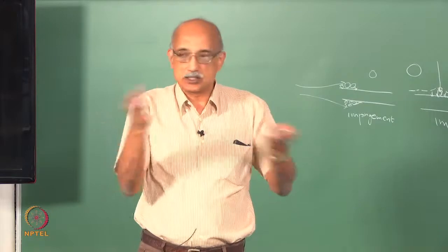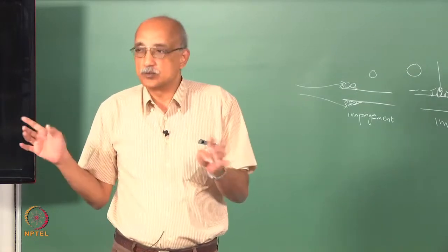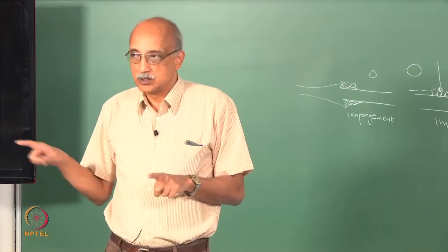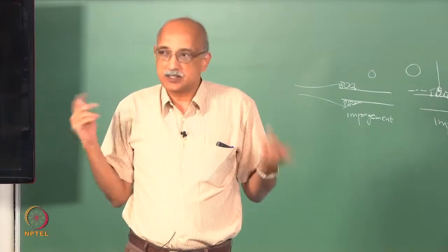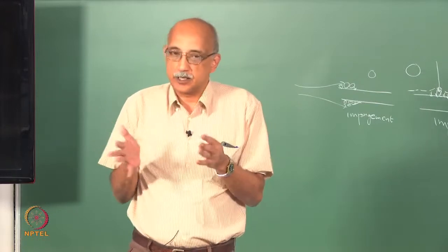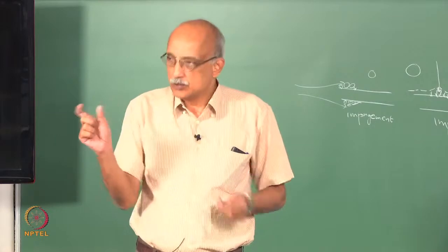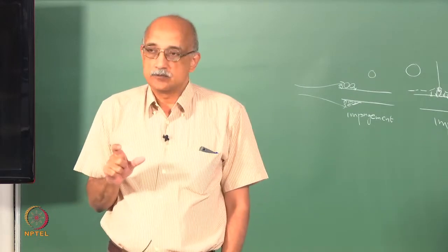The reason for that is this room, even though it is a clean room, it is not a clean room. Clean room is two separate words, cleanroom is one word. There is a big difference between the two. A clean room is one that has been maintained clean, but it is not designed to operate at a predetermined cleanliness level. A cleanroom, where you write it as one word, is a controlled facility where you manage